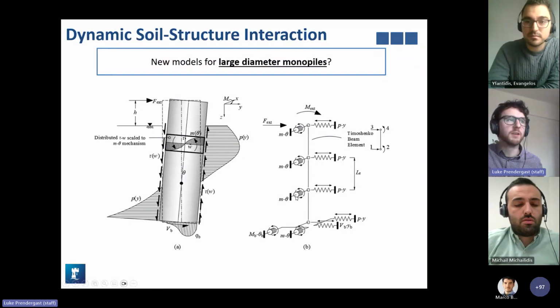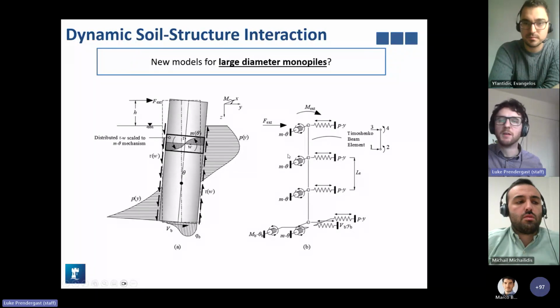This is supposed to be coming in the X direction, if we look at the schematic up here on the left. The idea is this is a rotational spring, so it affects the ability for the node to rotate, and this is the horizontal deflection of the same node. So there's no actual angle between them, in a sense. It's just the way that it's drawn. Does that answer the question?